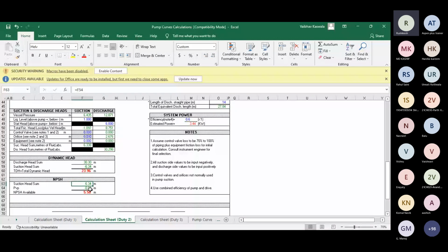Sir, will the pressure drop formula be the same as in the orifice meter, sir? No, it will be a little bit different. The equation will be different. Ultimately, it is the same only, the fundamental is the same, but it will be a little bit different. Just a minute, I will see. It is basically based on the orifice discharge coefficient, delta P, density, and the ratio of the inner diameter and the pipeline diameter, right? Beta is there, the d by D ratio.